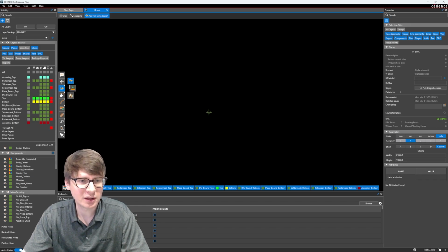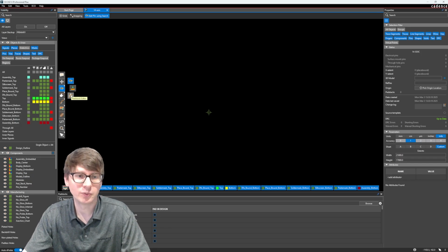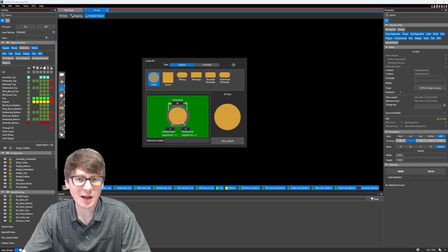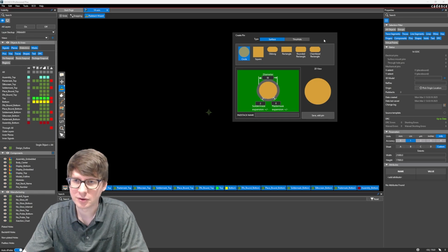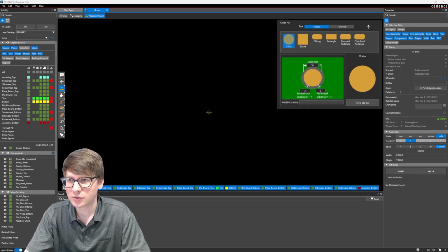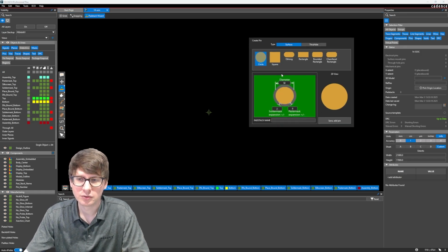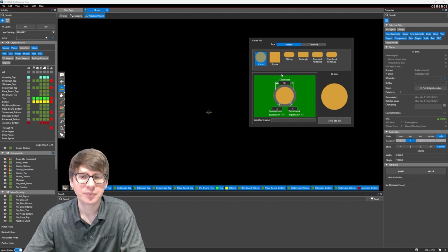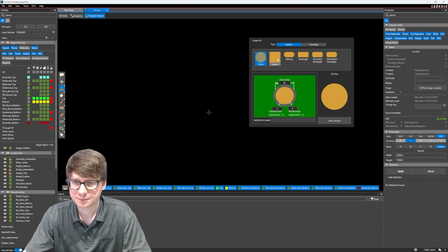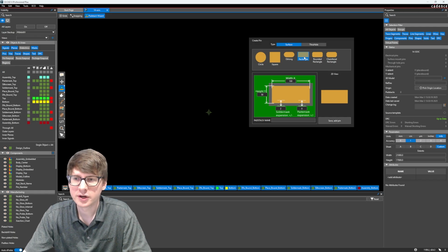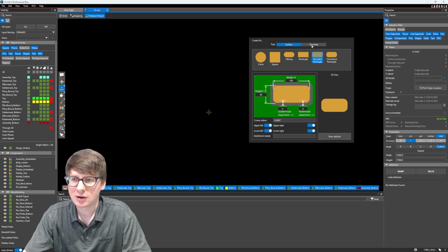But in this case, if we right click on here, we also have these options of the Add Pad Wizard, as well as using the tried and true padstack editor. Now the Add Pad Wizard, you can either have it floating or actually no, this one is only floating at this time. Basically allows us to very quickly create a pad, which will then create a padstack file for us and place it in that same directory. And here you can see we can pick things like, what is the shape of it, right? Rounded rectangle. What is the dimensions, right? Your width of the pad, the height of the pad, your solder mask and paste expansion, what is the corner radius, etc.